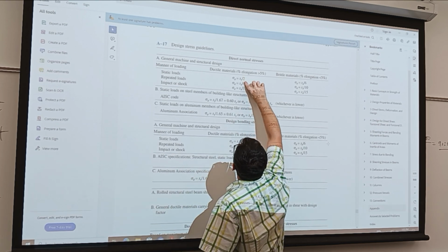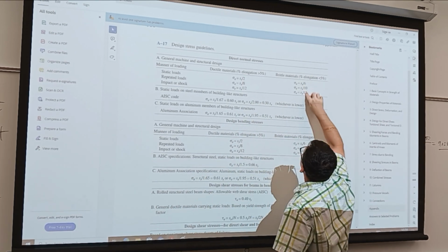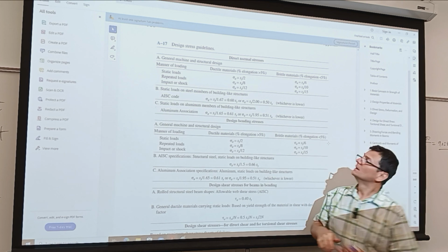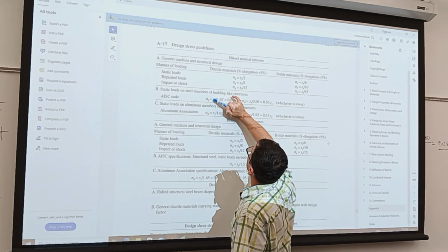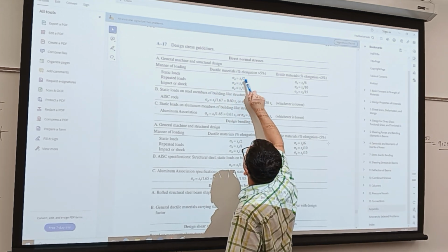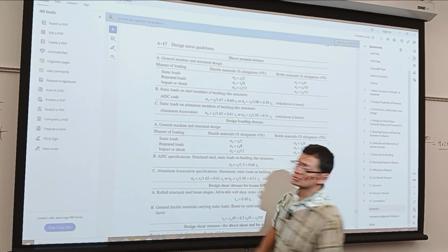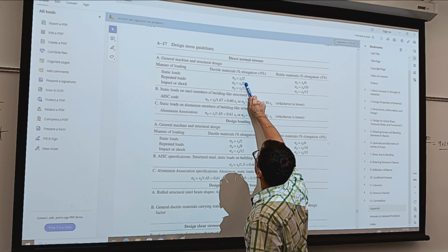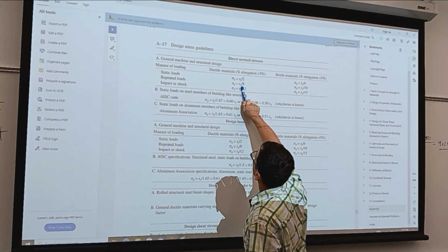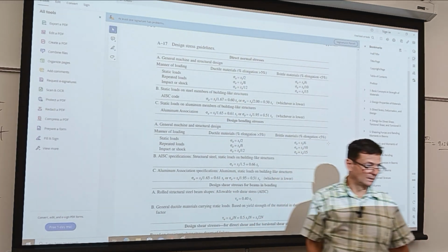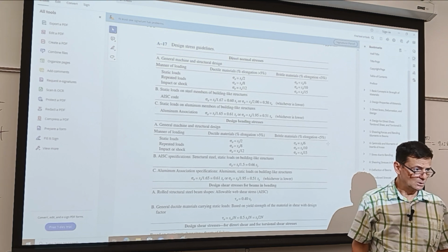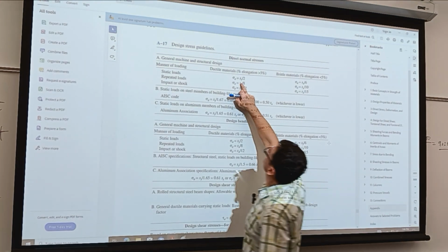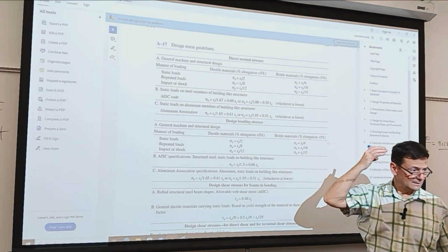Essentially, you look at these numbers and they are design factors. We call them N, but here it shows just a ratio. So design stress, yield strength divided by 2, this corresponds to a design factor of 2 with reference to yield strength. This is a design factor of 8 with reference to ultimate strength, SU. That is ultimate strength. Does it make sense?